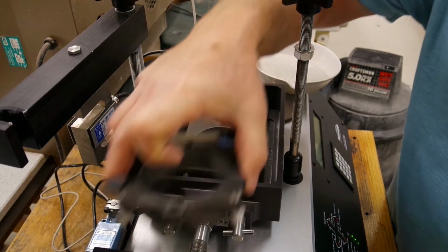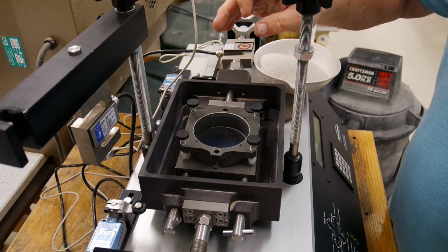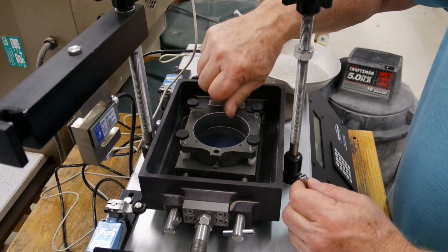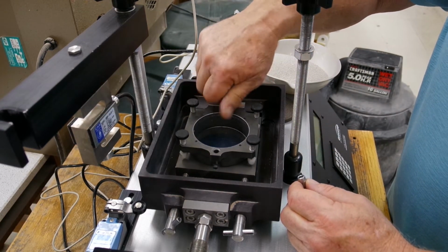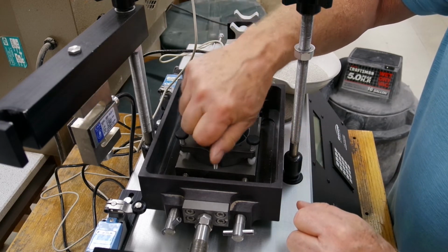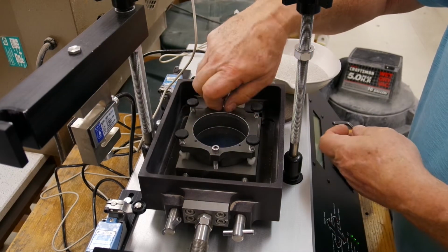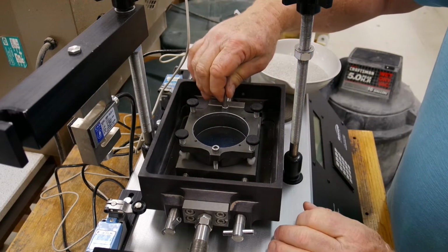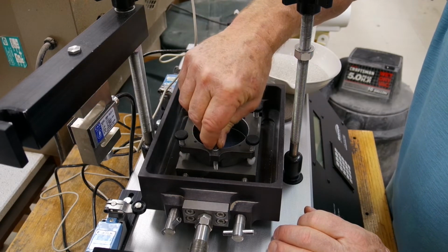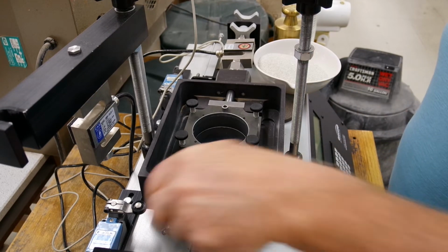To do this, we will place a porous stone in the bottom of the chamber, then place our bottom and top portions of our shear mold into the chamber. Make sure that the two pieces line up. We would have initialized the machine to return it to its start point so that the top and bottom of the mold line up. If they don't, we will need to move the shear screw so that they do. Once we are lined up, insert the alignment screws.